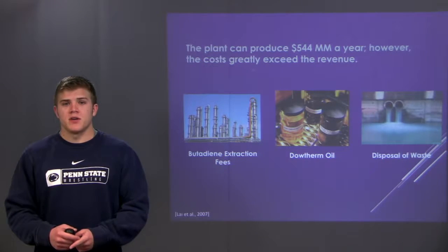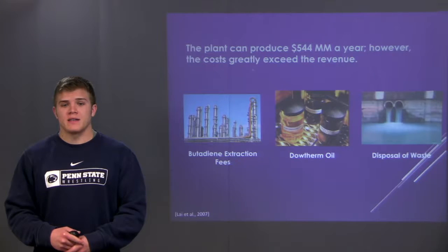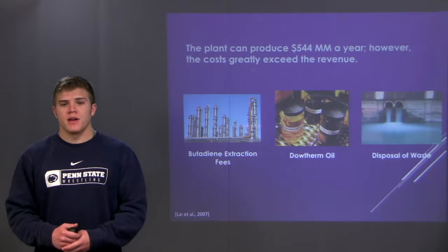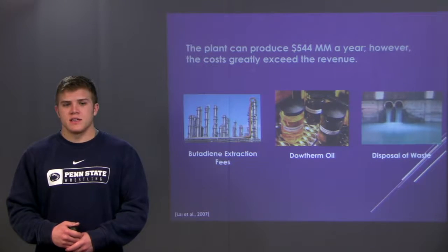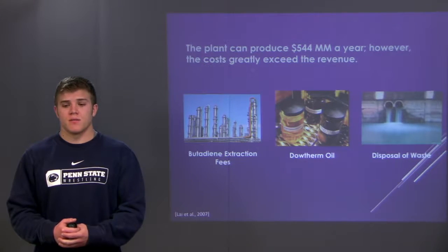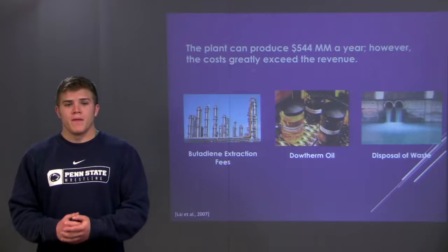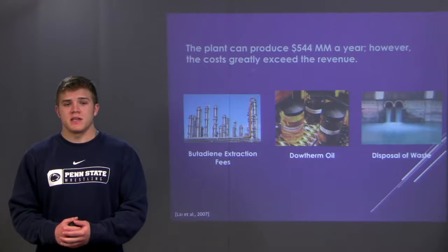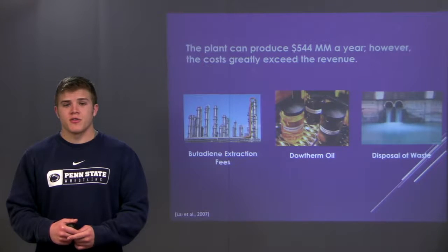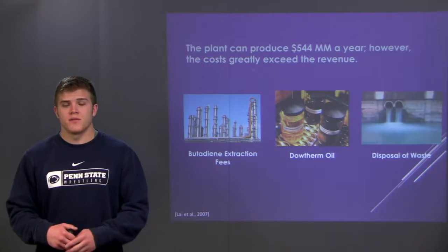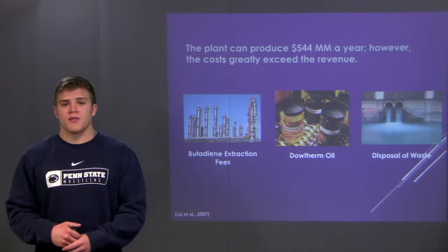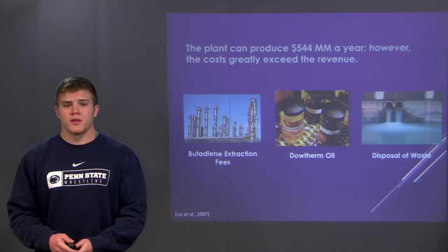There's benzoic acid produced throughout our process that, while it could be sold as a product, in order to separate it would grossly exceed the extra revenue we would gain from selling it. And so, in order to dispose of this, it has to be sent to a liquid incinerator, as benzoic acid is very corrosive and cannot just be disposed of with wastewater. And this cost totals 3.33 cents per pound styrene produced.